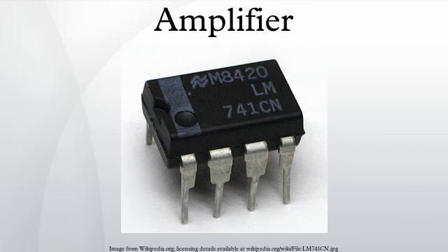Stereo amplifiers imply two channels of output, though the term simply means solid sound. So quadraphonic stereo was used for amplifiers with 4 channels. 5.1 and 7.1 systems refer to home theater systems with 5 or 7 normal spatial channels, plus a subwoofer channel. Buffer amplifiers, which may include emitter followers, provide a high impedance input for a device that would otherwise draw too much current from the source. Line drivers are a type of buffer that feeds long or interference-prone interconnect cables, possibly with differential outputs through twisted pair cables.